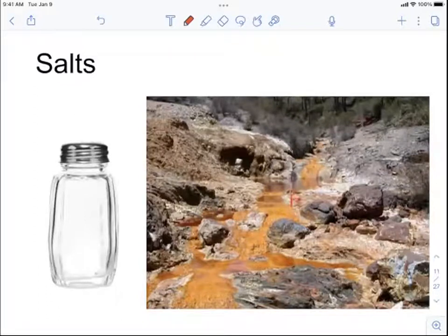And if you have ferric ion in the water, then you're going to have an orange or red color, right? These ferric ions are going to lead to the hardness of the water, right? Once you boil the water, you can see some sediments in there. That's it: ferric ion is a typical hardness ion that we have to remove in the water treatment process.